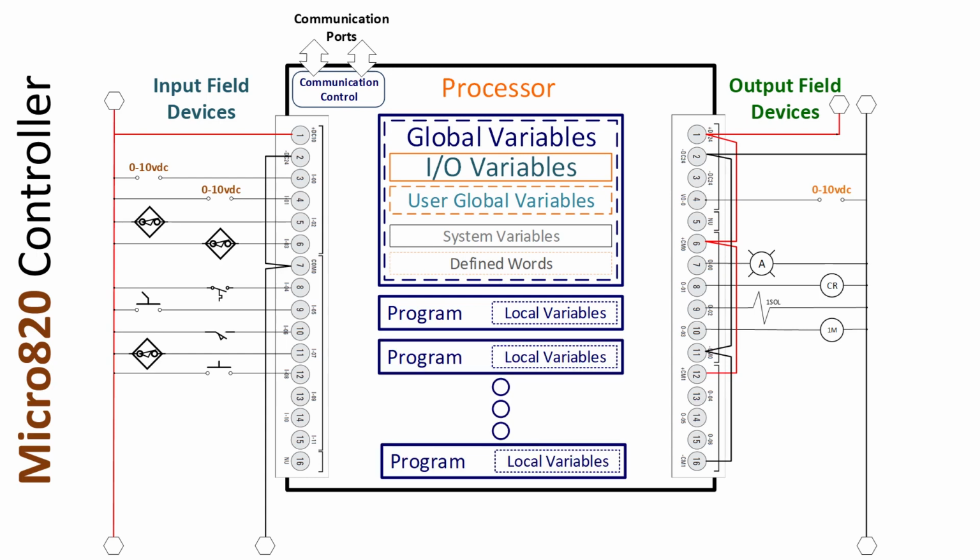Global I/O variables are determined by the embedded I/O count and type, and any plug-in or expansion modules. The types are fixed because they are module-defined data types, which means the electronics has a fixed data structure. It's all pre-named and all predefined. So the I/O variables, you cannot edit those. You can change the size of that data table by adding or removing expansion or plug-in modules.